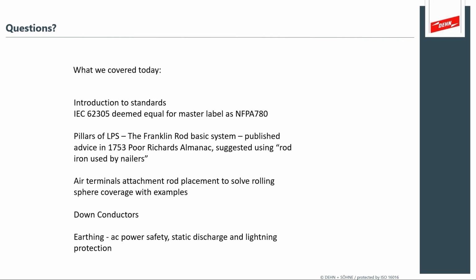Yeah, you inject 10 amps, and then it looks for what should be a low impedance if you're using the foundation, if that is a valid concrete. But it only is looking at the earth electrode. It's not really looking at your whole system. And you need to run that test without other things installed, otherwise, it'll obscure the actual effect of the earth electrode.